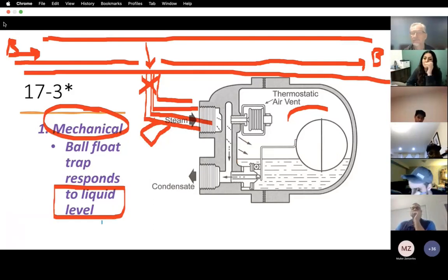this little housing, and this device, I'm going to say this device on my screen is about 6 inches tall. And the physical size of a ball trap could be about 6 inches tall. There it is, hanging on the lowest point of our steam line, which is a leg, a drain off of the line. And a little bit of water comes in, a little bit more water.